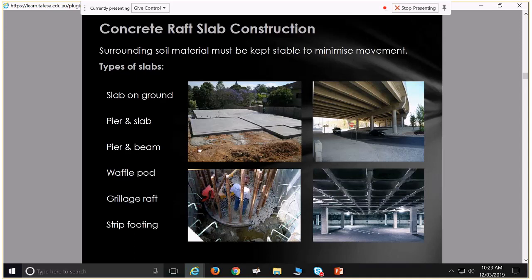So to get clay out of the ground, you've got the brickworks there, so for areas around that, they dug clay out of the ground. They just filled it up with just about anything. And so you can have a section that's all natural ground, and then a section next to that, which is a pit that has all been filled in. A way of bypassing all that fill material that may still keep compacting over time is to auger a hole right through that to lock into the natural ground underneath.